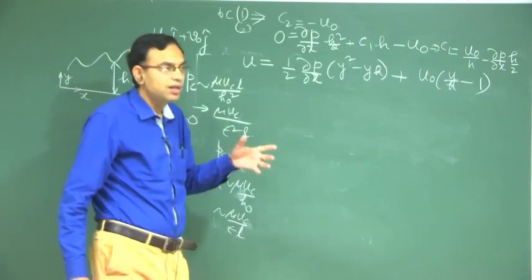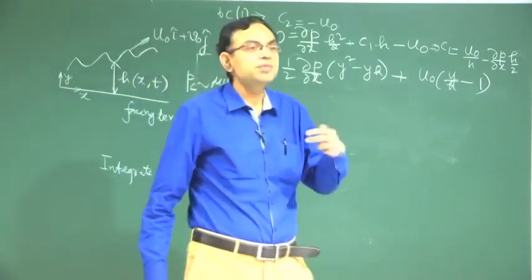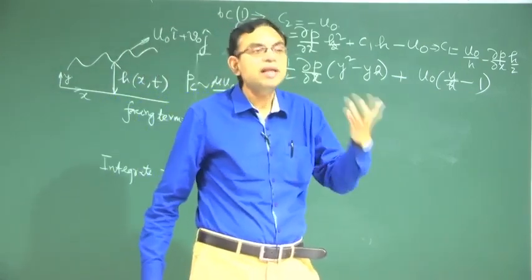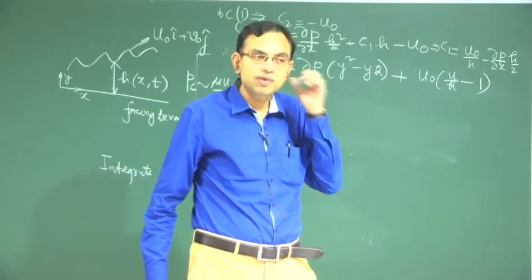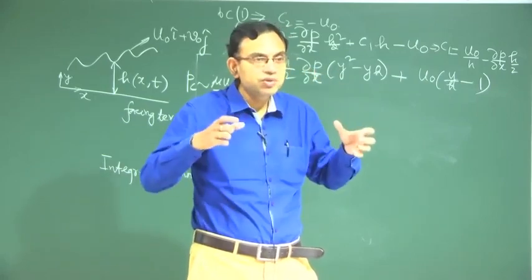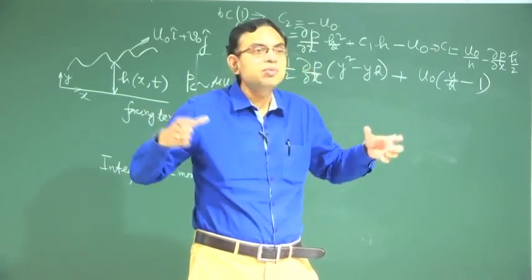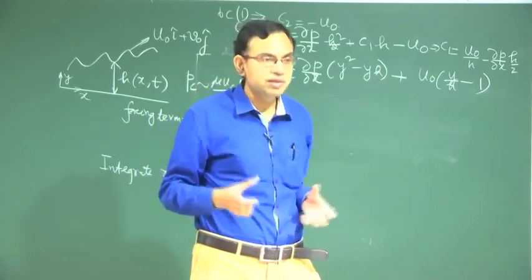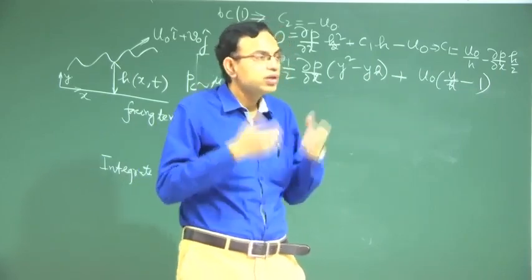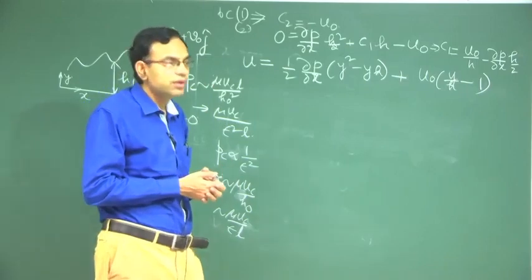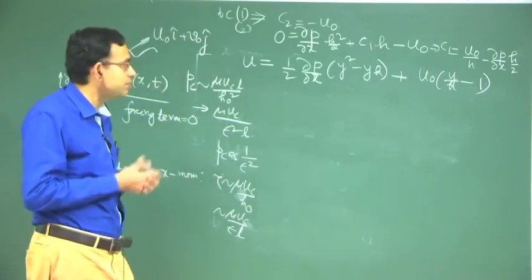Epsilon being small, the pressure is much more significant in lubrication theory than the hydrodynamic shear itself, and that is why the pressure distribution itself dictates what will be the force on the boundaries, and that is why we need to develop a governing equation for the pressure distribution, that is the objective.